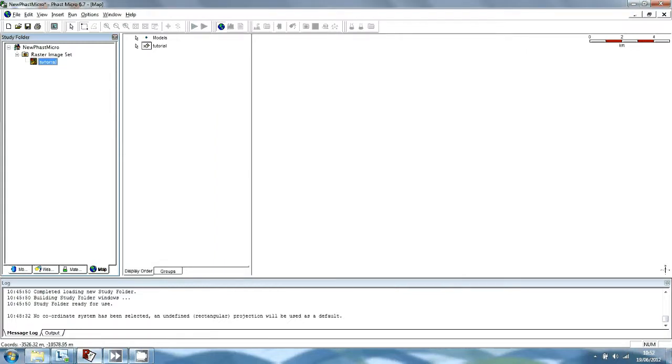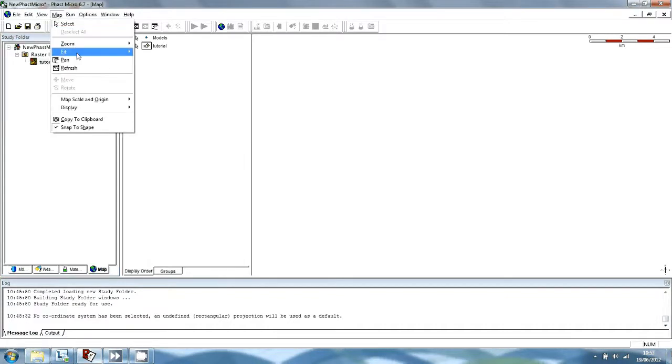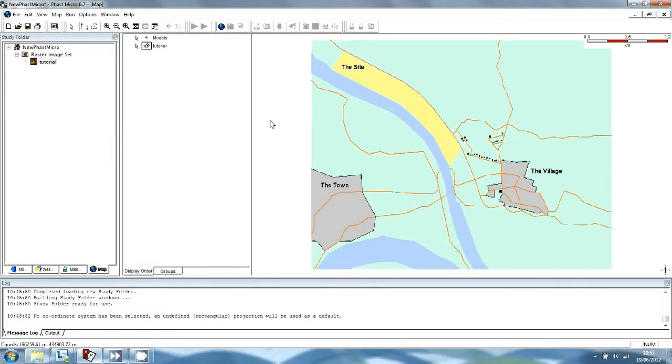OK this dialog. When you click on OK, the image will probably disappear from the map window because it has moved to a location beyond the scope of the window. Select Fit All from the map menu, and the map window will change to display the area covered by the image.